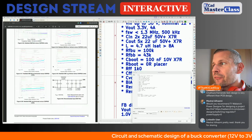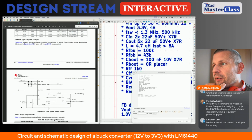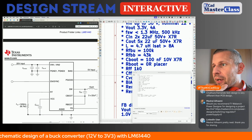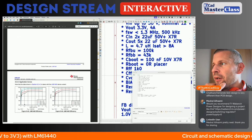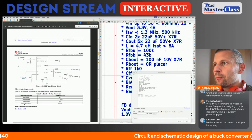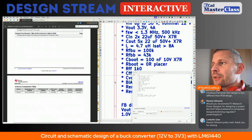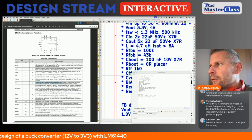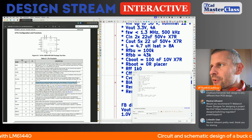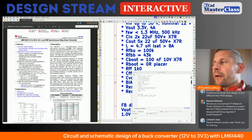I'm looking for the RT resistor value for the 500 kHz switching frequency, and I'm happy. Here is the value in some example circuit, but still I want to know what the calculation is. So let's check the datasheet, the pin section, RT. Yeah, here is the range of the resistors, but still I want to know the exact value.